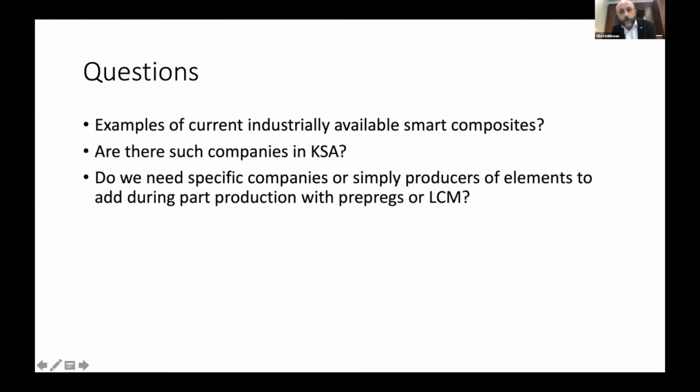And then there are people who come more from structural mechanics, who are really using composites, like long fiber composites, in which the type of 3D printing that they are using from the beginning is typically fiber placement or things like this. That is the way you are laminating a large composite structure, right? And there is a big gap between both worlds, which is the concept of consolidation during the printing. That means if you go to structural composites, you have a consolidation of the material, right? To make sure that you can ensure the level of mechanical properties you need for structural mechanics.